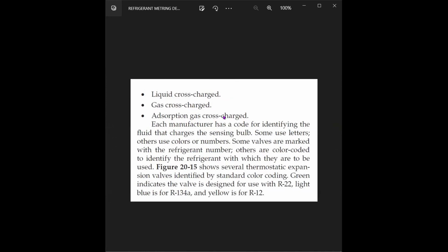After that the pressure will not increase, and the pressure rise will be very small, and near the maximum operating pressure the pressure drop is not that large. So that is one more reason why you operate it. You don't want the reaction of the TXV to be very large. That is also one reason we want to take a gas cross charge refrigerant.